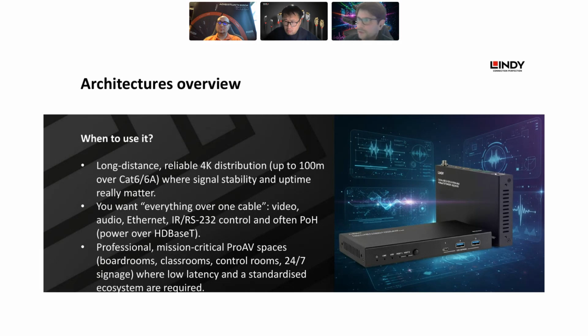When to use this kind of technology? For long distance and reliable 4K distribution, mostly up to 100 meters over a Cat6A cable, and where signal stability and uptime really matter.